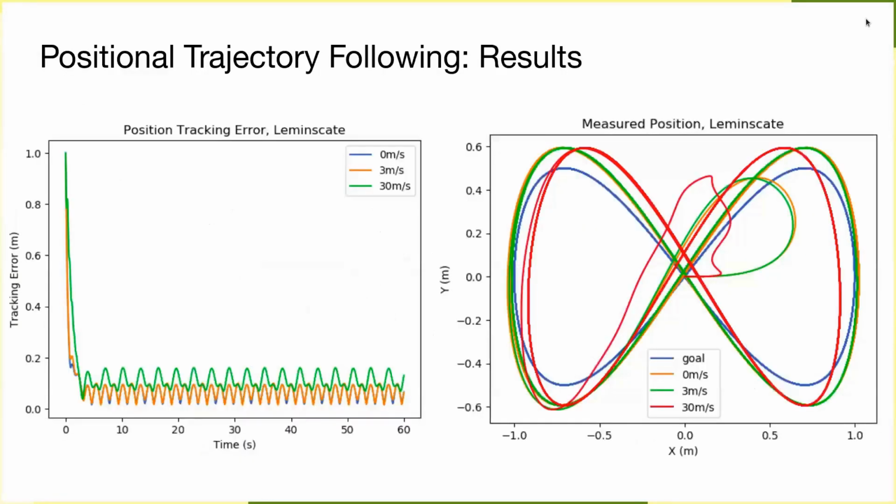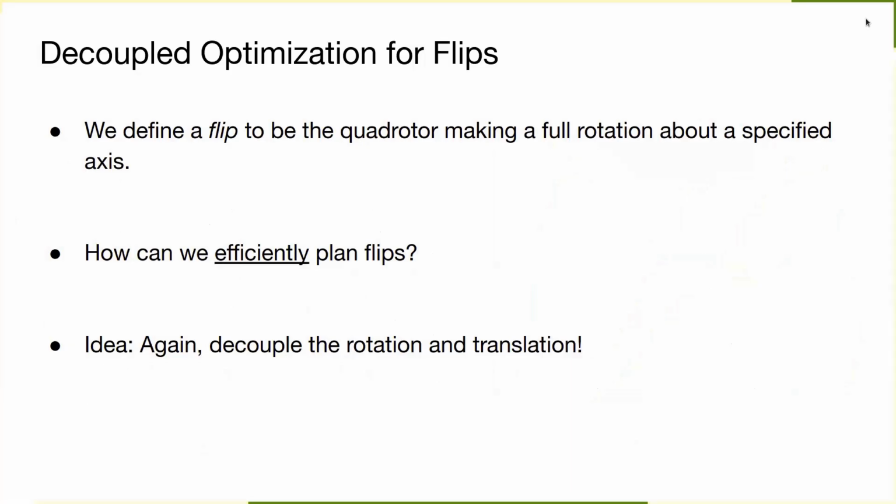Specifically, because of the high gain of our system, trajectories were seen to perform roughly similarly with and without air resistance and across our range of winds, without control input ever exceeding 2 newtons of thrust per rotor. However, steady-state error did occur, and the system would not converge on zero error. Next, we turn our attention to aerial acrobatics with the quadrotor.